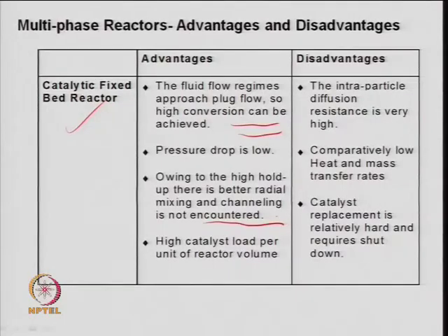So, one can look at the hydrodynamics to evaluate the RTD and try to find out the condition when the reactor resembles a plug flow reactor. That becomes very important in terms of the design of the reactor or selecting the best kind of reactor, and working under ideal conditions or making it ideal for the conversion. So, channeling is avoided or minimized in the case of the fixed bed reactor, and catalyst loading is high per unit volume of the reactor.